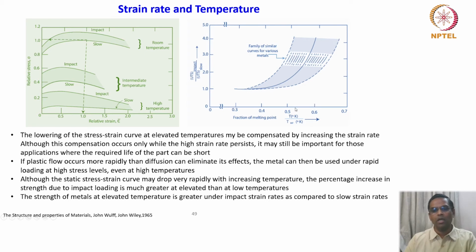Okay, most of it. So what is the microstructural change that will occur in this temperature range, that is 40 to 50% of the melting point? Most of the recrystallization and recovery processes rapidly start taking place at this temperature. So that's why it has also started responding significantly in this range. Okay, but here there is a division, the temperature range is quite high.